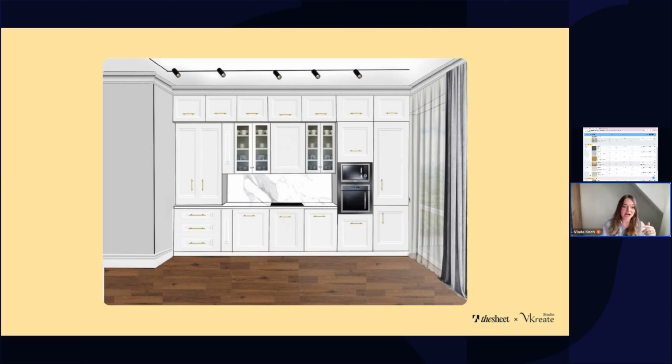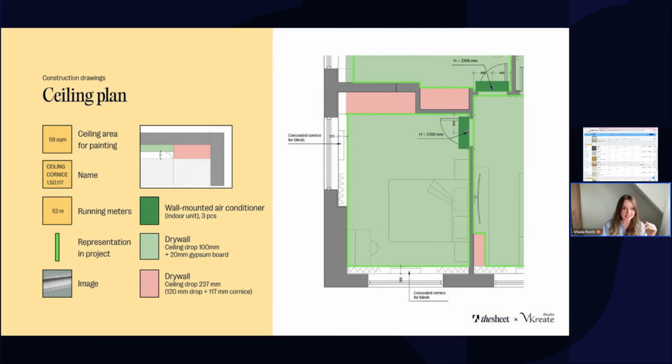That's why you have to drop your ceiling lower on the part above the kitchen, as I stated here, for example, in red, because your cornice has to have a support on the back to be held with the ceiling drop that you or your builders essentially would do. That's why in all the kitchens, I would always drop the ceiling lower.